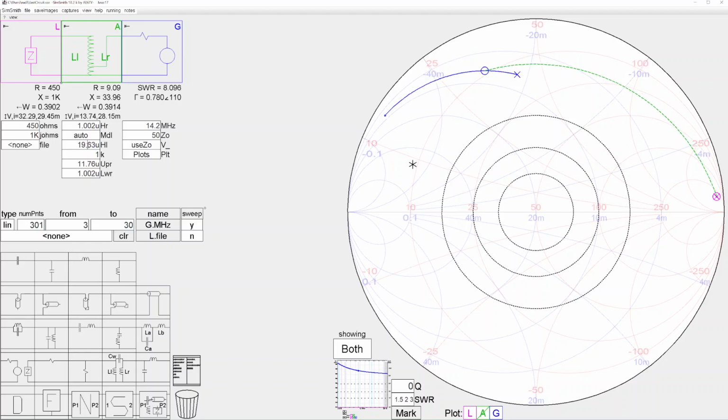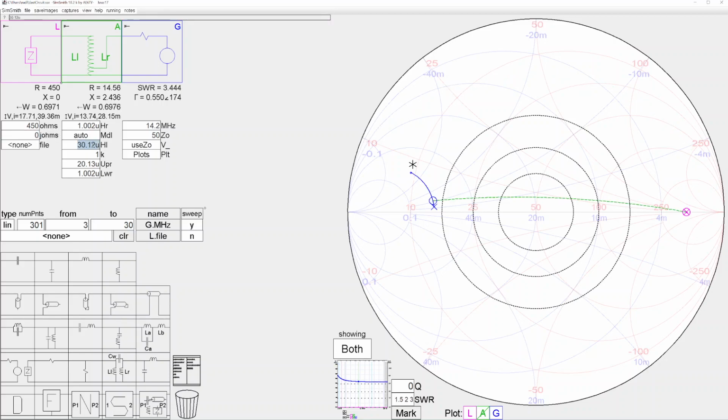Okay, so you can see that when we have reactance in here, we're having a hard time solving this. It's not really getting us to 50 ohms. Let's pretend for a second that we have zero reactance and see how much easier this is to solve with close to zero reactance. Aha! Look at this. Now I can back this off and I can get a little closer to my 50 ohms, but I'm not quite there yet.